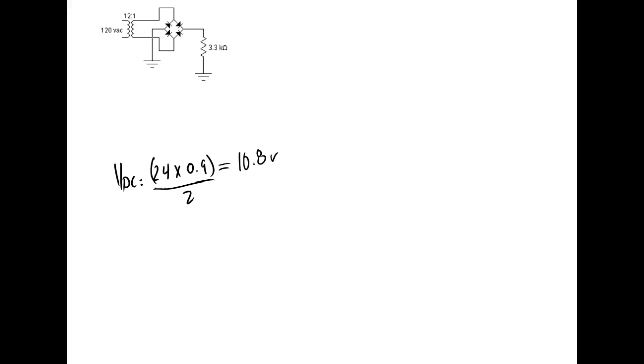0.9. I showed y'all how it came up. How did they come up with this? So first of all, the factor, or what we call the transfer function, or whatever you want to call it, would be the output. So what we get out we calculate by V peak times 2 V peak over pi, which would be 0.637. Now that's our output. Our input is volts RMS, right? We calculate volts RMS by taking V peak times 0.707.